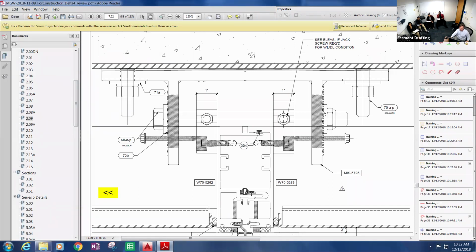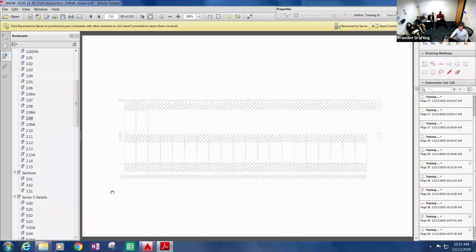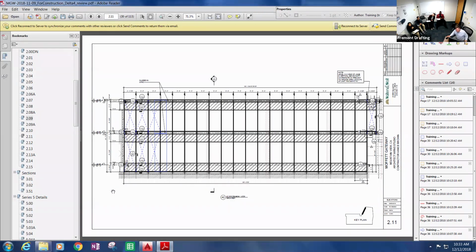So it's going to be trying to bend in dead load, and then it's also bending in wind load. It's bending out, from the same points. So there's deflection on bolts too, not just the mullions and glass. Okay, so that was tributary.